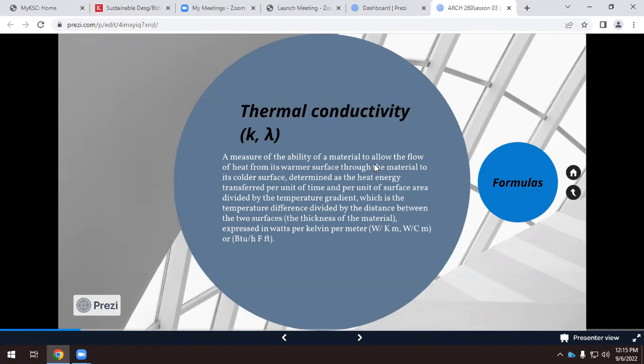So if we have very high thermal conductivity, we can feel that there's a lot of heat going from this object at 98 Fahrenheit to this one. So if we have exactly the same objects at the same temperature, 75 and 98, but this is a very low thermal conductivity, then what we feel is that the rate at which we are moving the heat is very low.